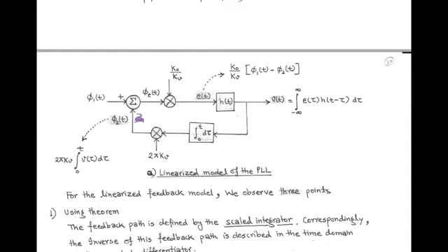And according to the equation, the angle phi 2 is equal to 2 pi kV integration V tau d tau. Here V tau is the control signal. So in PLL, the feedback path has a voltage control oscillator, and here to get angle phi 2, we take the transfer function as integration of d tau with limit 0 to t.